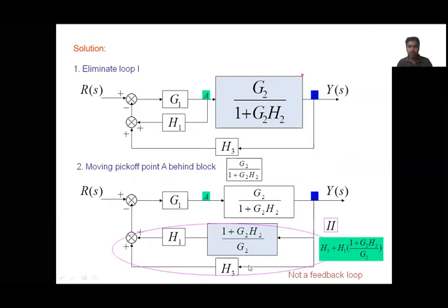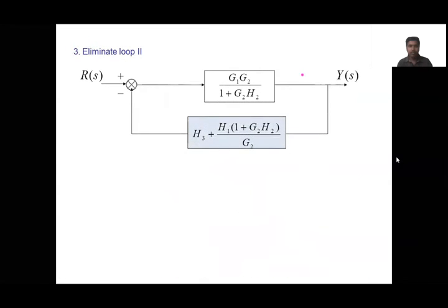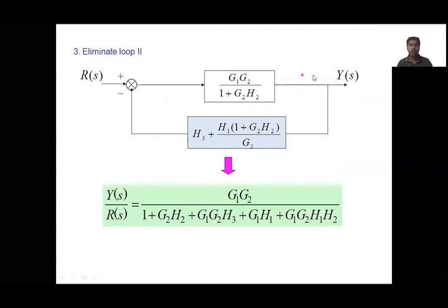So this parallel connection will give this summation, and this cascade is like a multiplication, we already know. So here the cascade connection, here the parallel connection. And now we'll see this total is like a single feedback loop. Therefore, if you write this as total G and this as total H, then G by 1 plus GH, if you write and simplify, you will get like this. This is a way how to reduce the complicated block diagram into a simplified version.